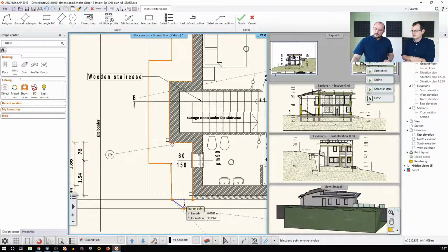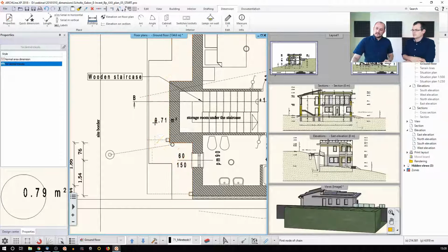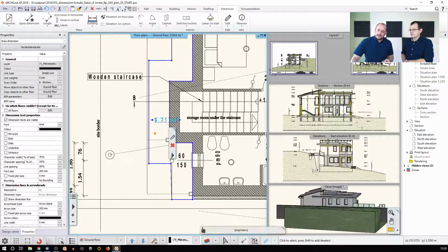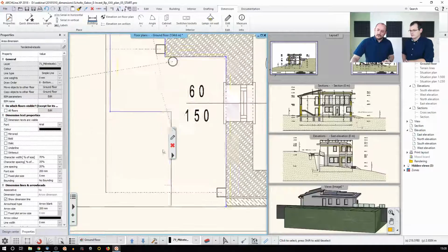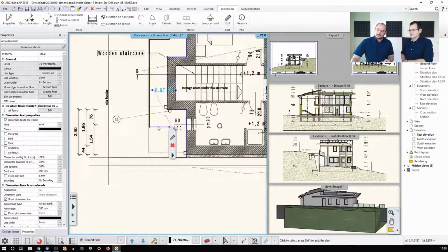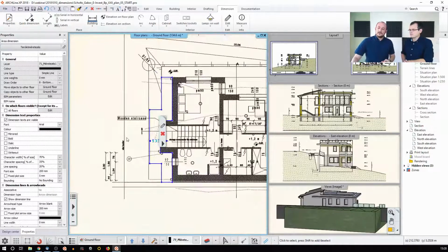And then whatever I did with this one, I actually made a mistake over there, so I can also show you how to fix that. The software measures this. You can say, okay, enter, and then place this text somewhere, and then the software recognizes, okay, that was the area. Now we work in the metric system, and when you select it, the software keeps the original contour, and then you can make fixes, move this node somewhere else, and then it will update itself. So this is how you can measure certain areas.